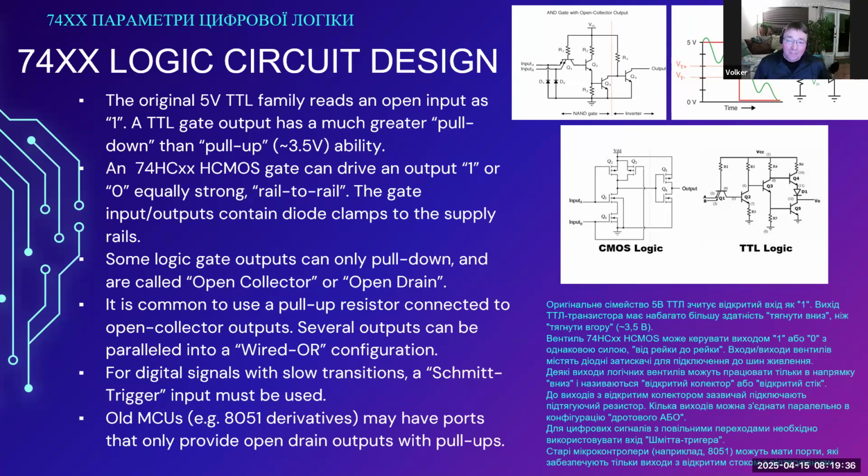So you have to imagine that every output, and actually most inputs as well, have two diodes from the output directed to the supply voltage, and from ground directed to the output. These diodes are not shown, but they're important when you get to high side drivers, because those protection diodes prohibit certain configurations if you're trying to create a high side driver the same way that you're trying to create a low side driver. We'll get to that, hopefully.